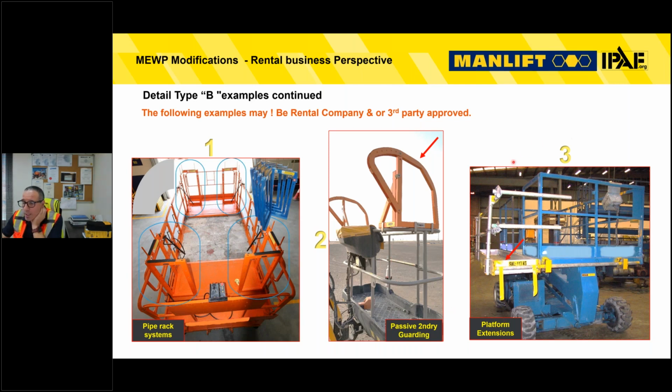Here's quite an old one, number 3, where we have an extension deck attached to the side of the scissor lift, and I'm wondering if that was done with the correct process. Does the MEWP need to be derated with its safe working load? Can it still go to the correct height, the height that it normally goes to? What are the stability changes for that mobile elevating work platform? We have to consider what indeed are the maintenance requirements now.